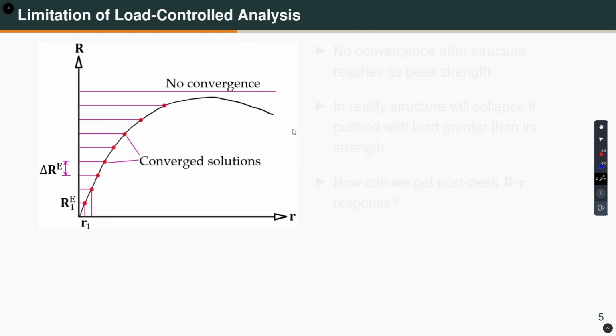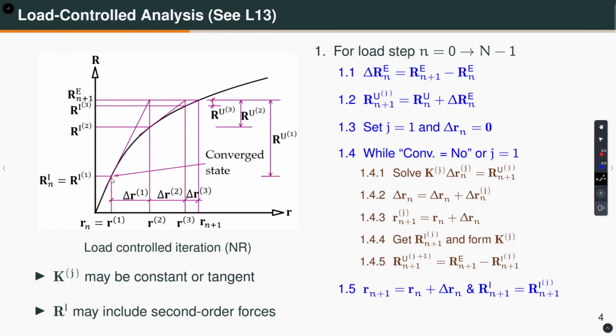Now, when you are doing a load control analysis, what are you doing? You are actually applying load in small steps, and in each step you are solving a linearized problem, right. If I go back, in each step, from here to here, from this to this, you have applied this, and in each step you are solving a linearized problem, iterating and achieving this solution, isn't it?